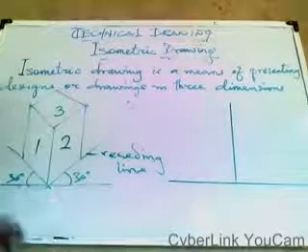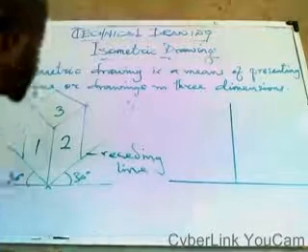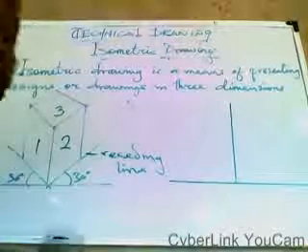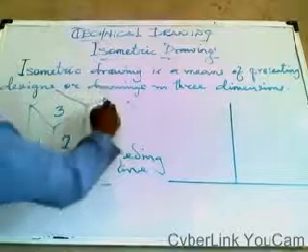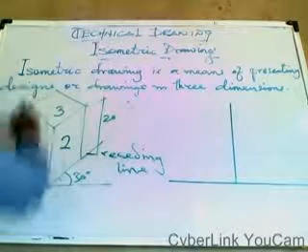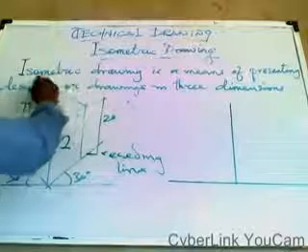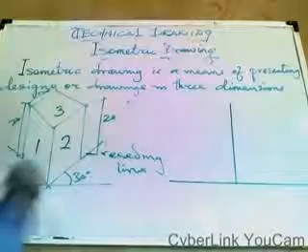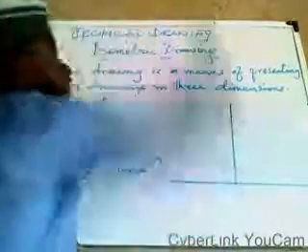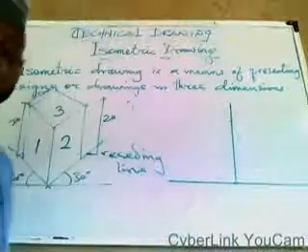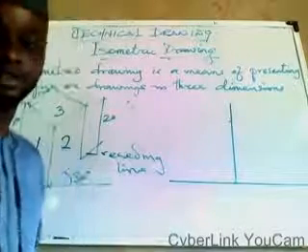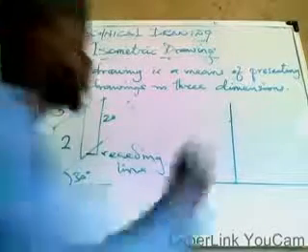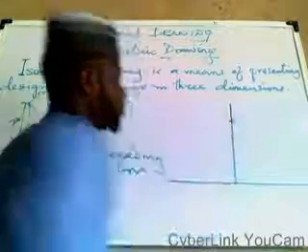This is the line. So, in the drawing, you will be given some dimensions. They may say from here to here is 20, this one is 20, this one is 20, all those things. So for you to measure this 20 now, you come here, you mark 20. This line, you can draw it to any length. And whenever you want to start the drawing of isometric drawing, you must start with faint lines, construction lines. So let's say from here to here is your 20, stop here.